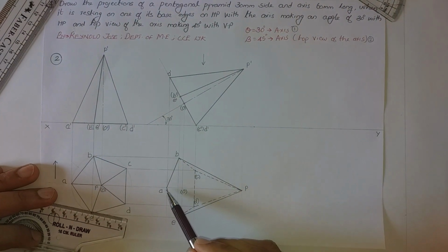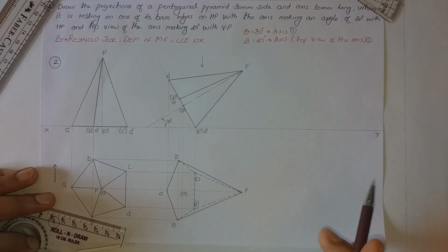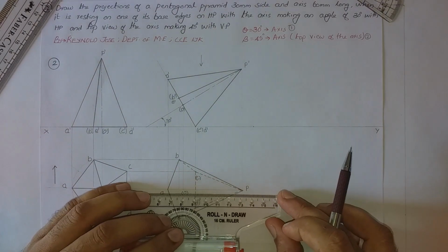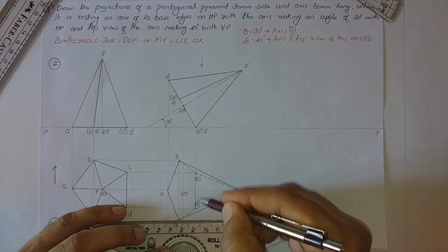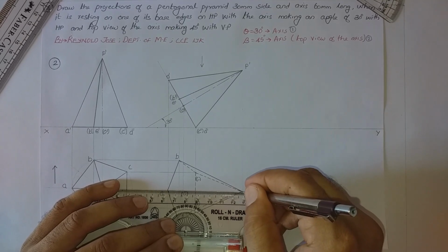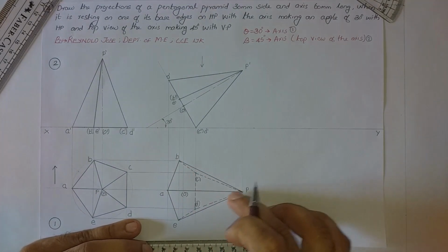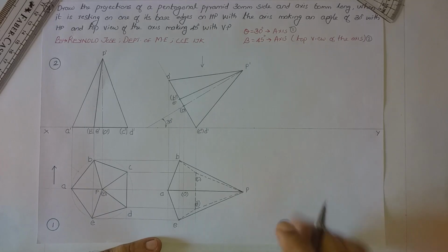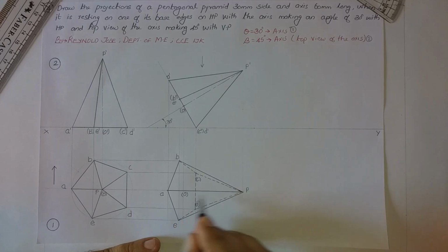Now all the base edges AB, BC, CD, DE and EA are completed. Now we shall check the slanting edges. So PA, so this is PA. When you are trying to draw PA, it is actually crossing a confirmed hidden line. So this line will be visible. PA will be visible. PB is already here, PC is here, PD is here, and PE is also here. So we have done with all the slanting edges. We are unable to draw the axis PO because already we are having line PE here.